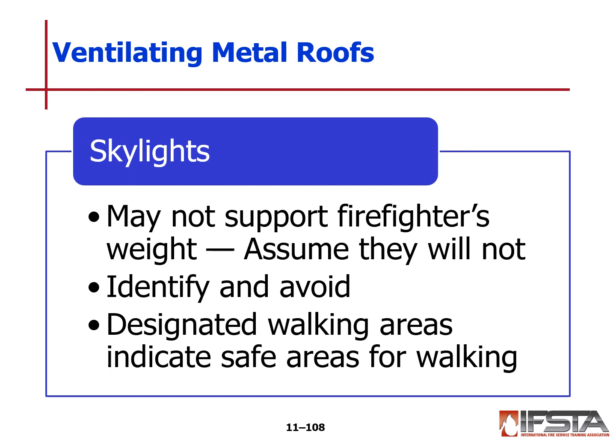Skylights. Remember that skylights are not going to support firefighters' weight most likely. Assume that they're not going to. So don't step up on them. Don't sit or lean on them. Identify and avoid designated walking areas. Indicate safe areas for walking.